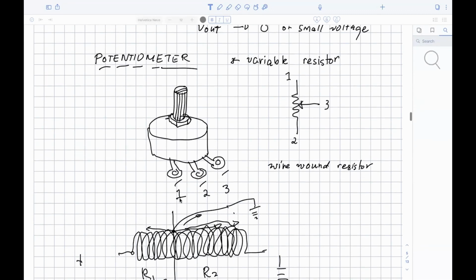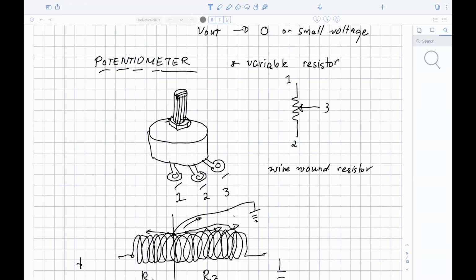But what's crazy is this. In our first experiment, this knob is rotating, right? What if we attach a ruler or a stick here? When we rotate it, the voltage will change. When we rotate that stick, the voltage will be different each time. What if we use the potentiometer as a rotation sensor? We can measure angles, guys, using a potentiometer.